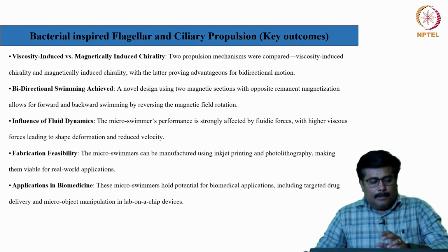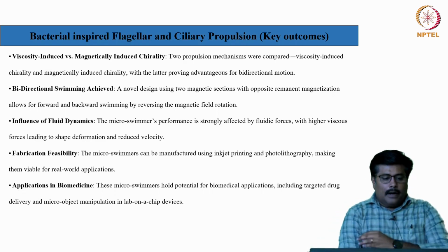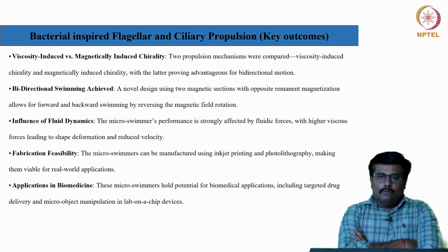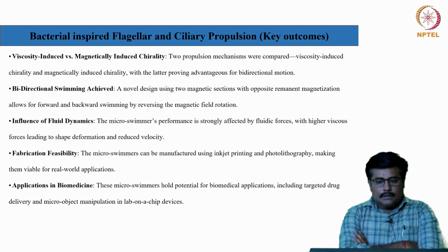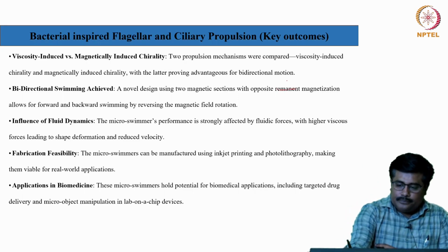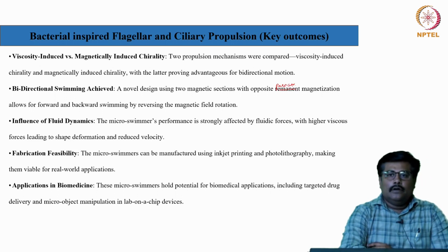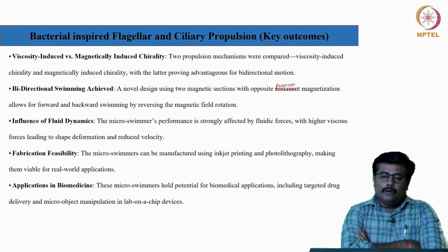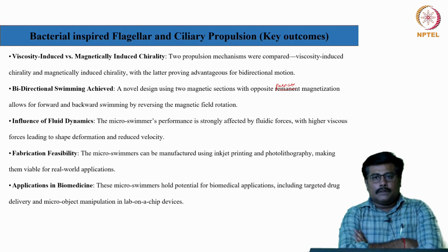In this particular case, bidirectional swimming is achieved. It is a novel design which uses two magnetic sections with opposite permanent magnetization, which allows for forward and backward swimming by reversing the magnetic field rotation.